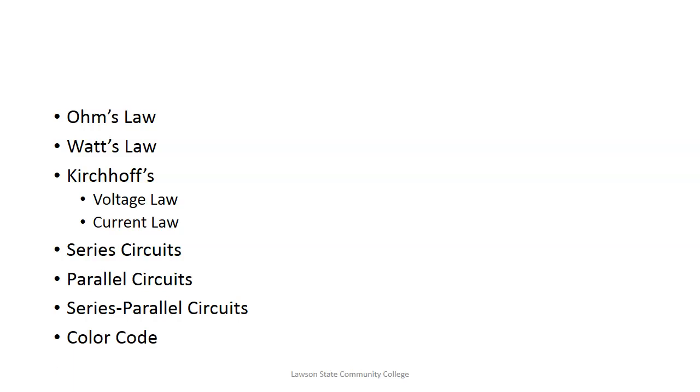Now, as you move through your training, you'll see that these same color codes are used by other devices besides resistors. They're used for inductors and they're used for capacitors. I've seen them used on diodes. But the color code is the same. So learning those color codes and those numbers that go along with each color would really, really be important as you move through your career on these different devices. Knowing that color code is very, very impressive.